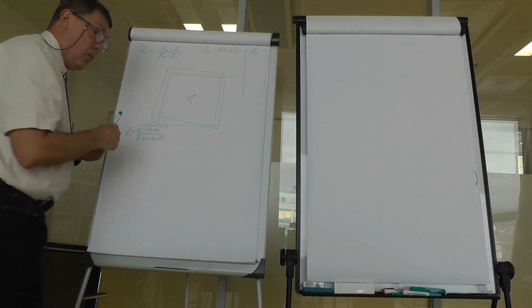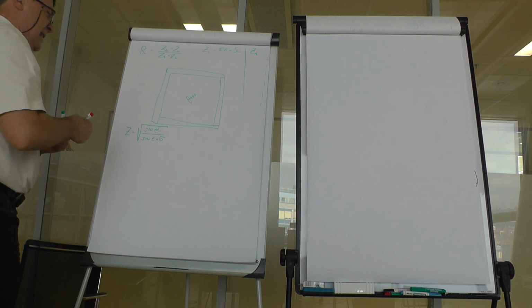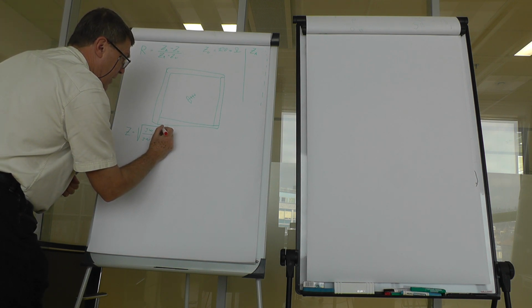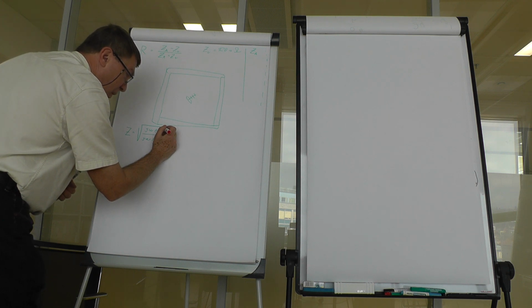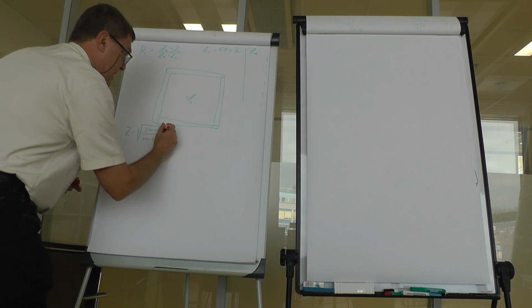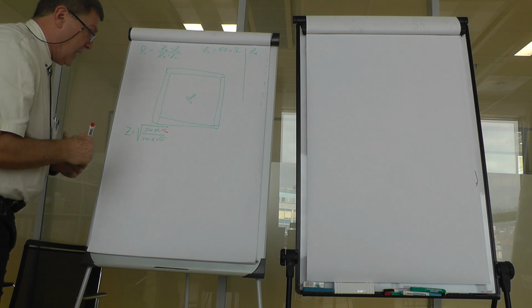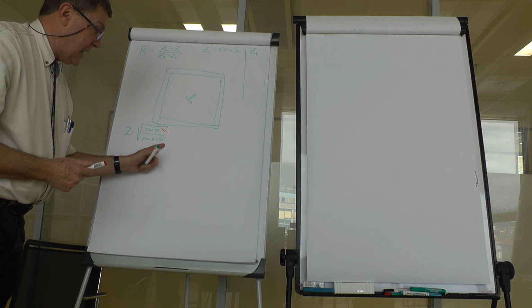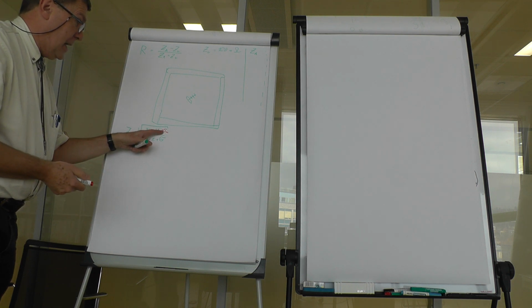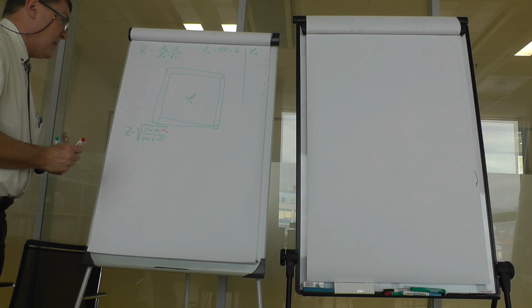And so for this purpose, the classic theory is enlarged by one term, which is the losses by repolarization of magnetic domains. Historically it's also denoted by sigma, like electric conductivity, just this must have a different dimension, so it's just a historic way to name it.